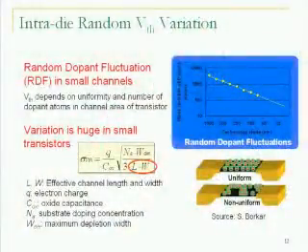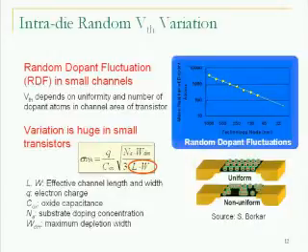The parameter that I am talking about is VTH. Remember that knob that I talked about regarding leakage? So two transistors with the same size, even if they are adjacent to each other, have different VTH values. This mainly comes from a phenomenon called random dopant fluctuations. For the sake of time, let me just say that, in previous technology nodes, you would have a big channel area, a big transistor, and thousands of atoms would go there.